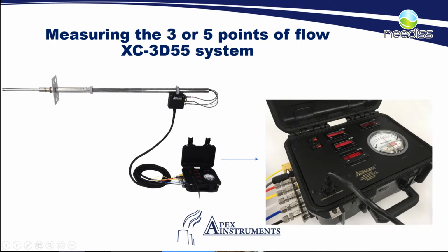We also need to measure our temperature for our calculations, our flow calculations, and our Magnehelic here, also measuring our impact pressure for our sampling. So this would be considered a manual system to perform method 2F or 2G. You would have to perform all of the calculations manually and have an understanding of those, and record all the information manually when you are performing this testing.